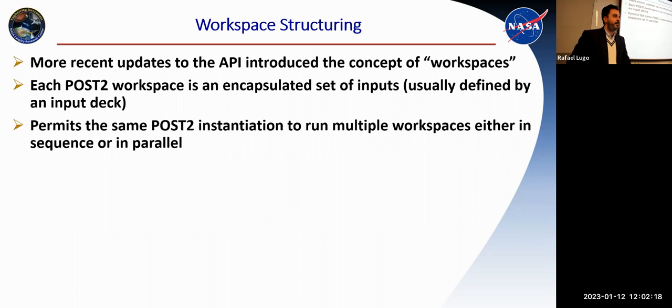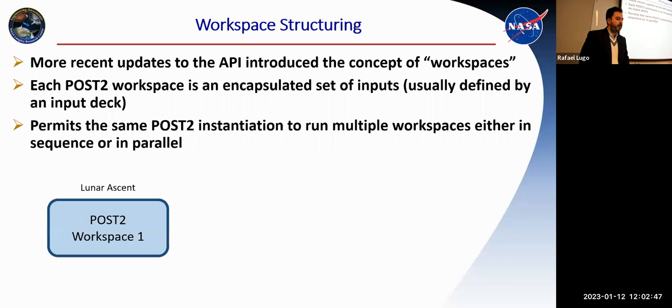I wanted to touch very briefly on a much more recent thing that we've done called workspace structuring. What is that? Well, what we've decided to do is say that each POST2 workspace can be an encapsulated set of inputs, which is usually defined by an input deck. If you have an input deck, let's call that a POST2 workspace. What we can do now that POST is multi-threaded and that we have an API, you can actually use the same POST2 instantiation to run multiple workspaces in sequence or in parallel.